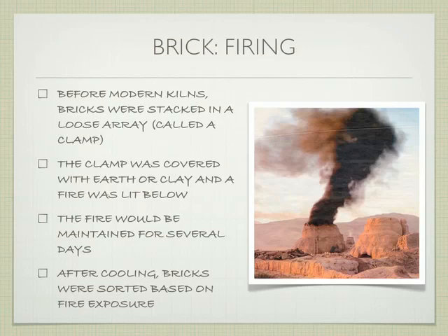After it's cooled, right, they'll open up this and start to sort through the bricks and pick out the ones that were fired evenly, keep those as the best ones. The ones that were on the edges that might have been fired somewhat unevenly, maybe they can use in less desirable places in the building where you can't really see them, or the internal structural places. And obviously, if they cracked or had some problem during the manufacture, those are the ones that get tossed out, right?